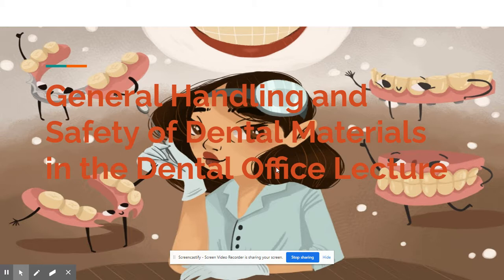Eye exposure may result in permanent damage or even blindness. Flushing the eyes at the eye wash station for at least 15 minutes and immediate medical attention are recommended. Exposure to HF is not limited to contact with skin and eyes. Inhalation of this potent acid is of equal concern. Adequate ventilation must be used.